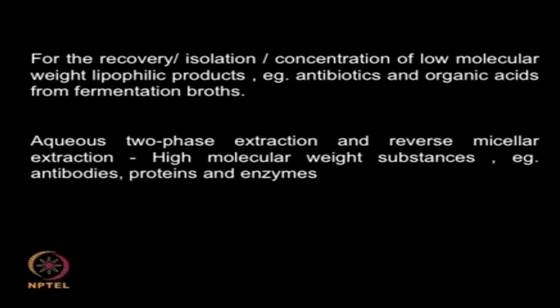So it is ideally used for low molecular weight lipophilic products like antibiotics, organic acids from fermentation broth, or I can use an aqueous two phase extraction system for high molecular weight substances, antibodies, proteins, enzymes. So this technique is widely used for a large number of separation and purification downstream processes. It is a thermodynamic process, as I said, because there is an equilibrium between the streams that are leaving the stage.